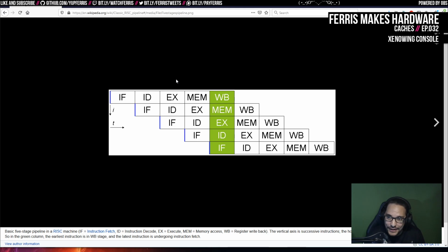Right now, the way I'm actually implementing this is I have each of these different stages as different hardware units. But to simplify things, I just have a little state machine that runs an instruction here, then this stage, then this stage, then this stage, and then it will go and get the next instruction. So I'm basically executing it the dumb way, even though I have a lot of hardware available for the fast way. So I need to change that.